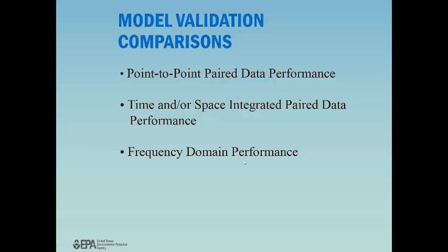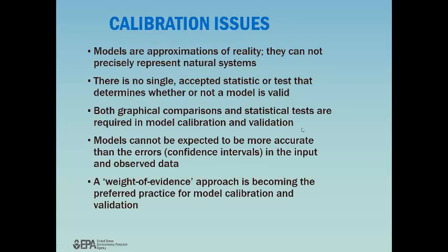Or you can also look at the frequency domain. What percent of time, like a flow duration or a concentration duration frequency, you can generate that from the model, and it depends if you have enough data, especially concentration data where you may not have as many samples. You may need to break it down to paired data samples and look at the observed data on the day and the actual simulated values for that day, and pair those up for only the days where you have data and do that kind of comparison. So there's a variety of different ways of comparing model results with observed samples, observed observations.